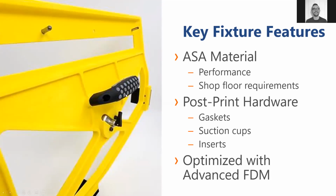On the flip side of this part, so of course this isn't the vehicle side. On the vehicle side, we wanted to avoid seams and we wanted to reinforce the part so that we wouldn't see any wear through to the sparse aspects of this. So we went ahead and did the face reinforcement tool that we've exemplified previously, and in that same selection also told GrabCAD Print to avoid any seams there. So that was some of the ways that we've optimized this part for additive manufacturing with GrabCAD Print Advanced FDM,